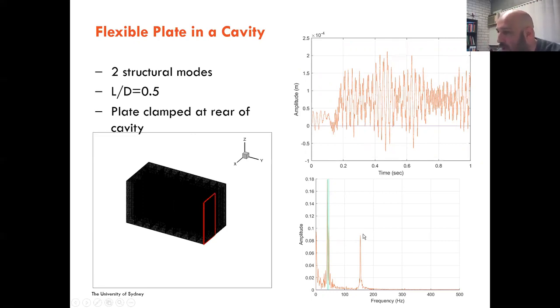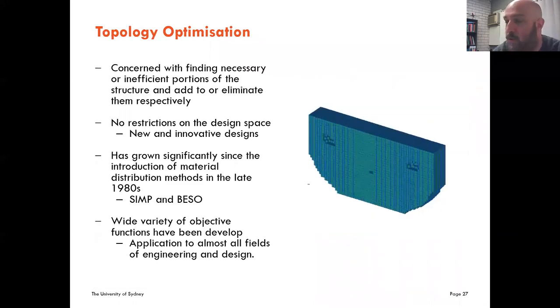If we look at the frequency spectrum here, we've got the structural modes, but then we've got quite a nice alignment with the actual frequency mode. And in this case, they've been shifted by probably around 10 Hertz from what we were getting from the pure rigid case. So there is quite an effect on the pressure that we will also get at the end from the simulation, which I need to analyze going forward.